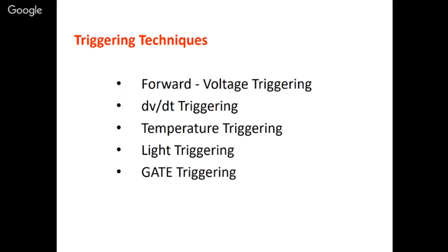So here there is a concept of capacitor. You can take a capacitor's charge as C dV by dt, and you can explain this. Whenever there is a sudden change in voltage, the capacitor charging current will also increase to a large amount, because IC is proportional to dV by dt. So this thyristor is just like a capacitor there, and when there is a sudden change in voltage, this charging current will increase. Because of that, triggering can occur. But these two methods are not preferred.